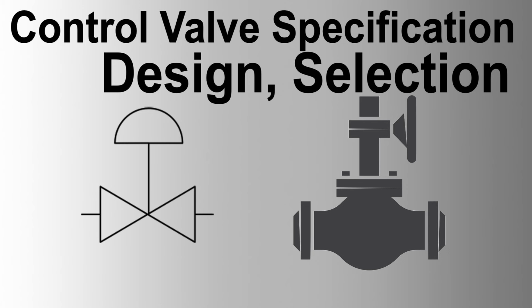4. Types of control valves. 4.1 Globe valves. Applications: suitable for high-pressure drops, precise control. Design: cage-guided, single or double-seated. Size: 12 to 400 millimeters, larger sizes available. Characteristics: versatile, turn-down ratio up to 50:1.